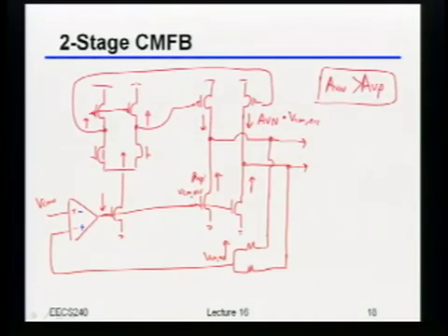There's not really any gain from here to here, because that's almost a cascode. But it gets gained up from here to here. It goes through there. Now it goes through this PMOS gain stage as well, and then shows up at the output. Whereas from there to there, all you get is just the gain of these devices. So most likely, this indeed is the larger gain path.